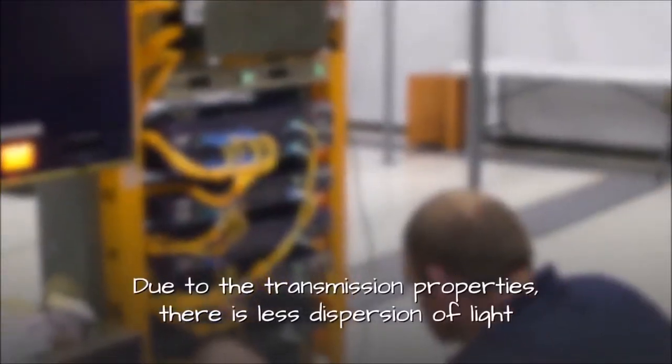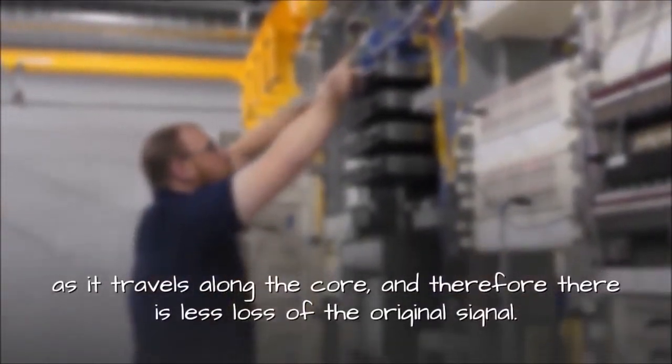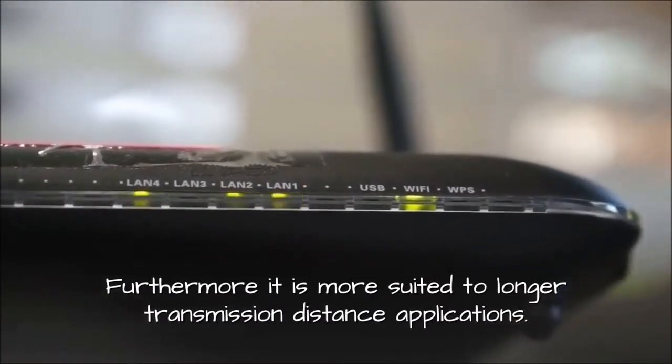Due to the transmission properties, there is less dispersion of light as it travels along the core, and therefore there is less loss of the original signal. Thus single-mode fiber is more suited to higher bandwidth requirements. Furthermore, it is more suited to longer transmission distance applications.